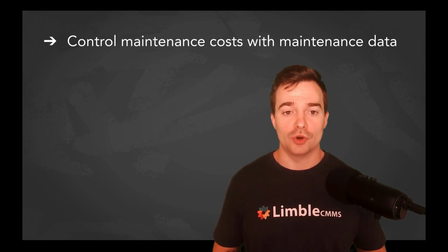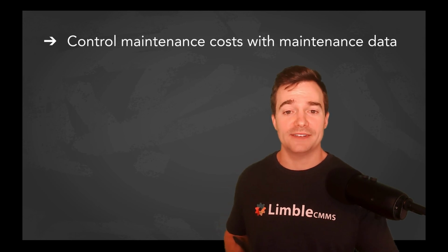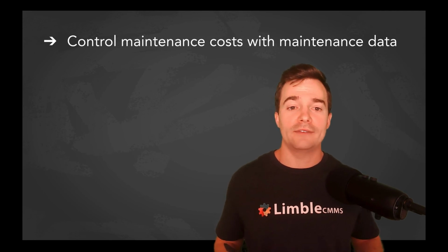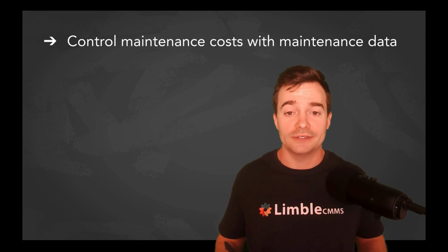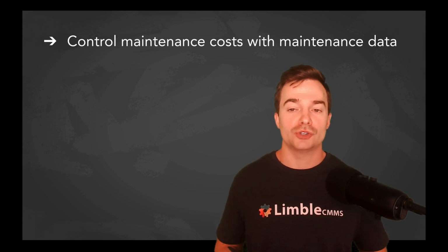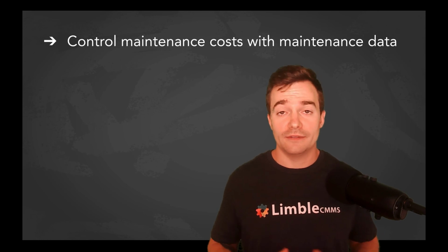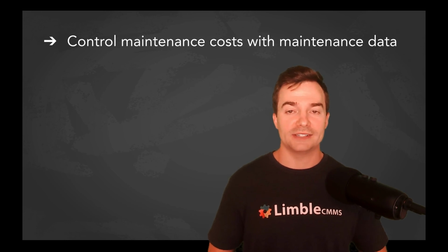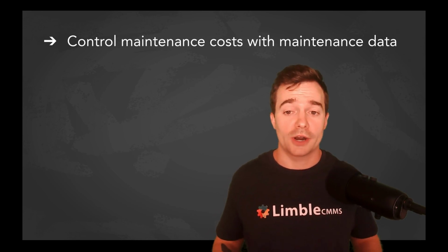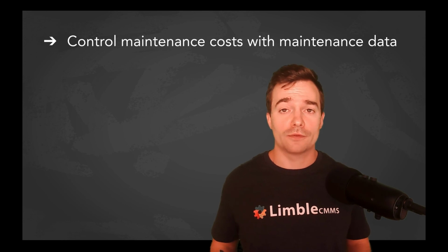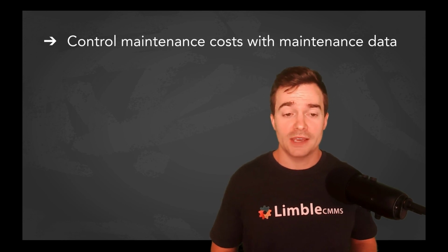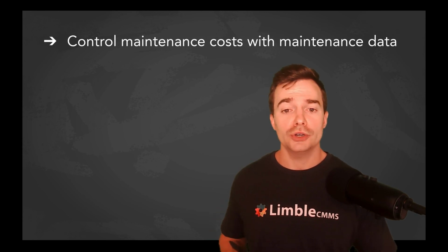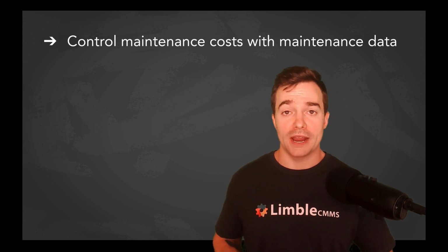Having the right data available is the most straightforward way to close expensive gaps and make cost-efficient improvements. Here's one specific example. Let's say you have an air conditioning unit breaking down unusually often. You can look at how many spare parts you are spending on repairs, so cost of the spare parts, and how many man hours are you spending on the maintenance and repair of the assets, so the cost of the technician, let's say per an hour. And if the breakdown meant that a room was unavailable for a while, which is a potential loss in revenue, then you can have some serious issues. So having all of this data makes it easier to conclude if the asset should be repaired or replaced.